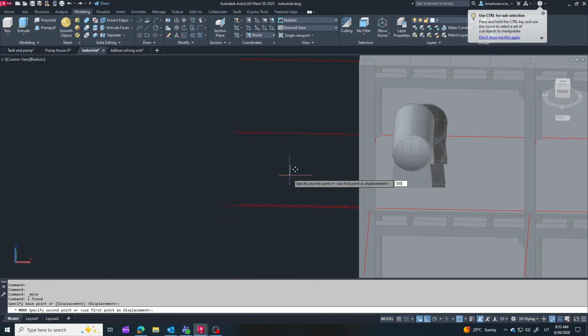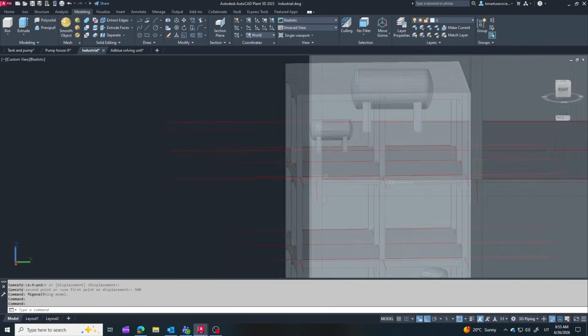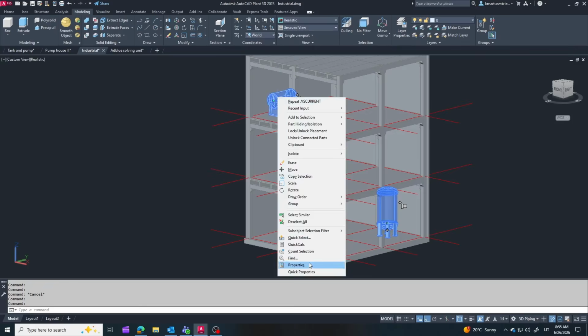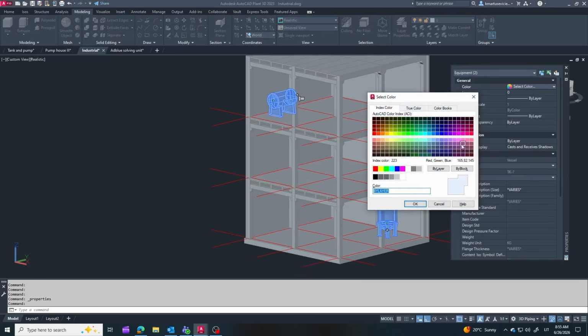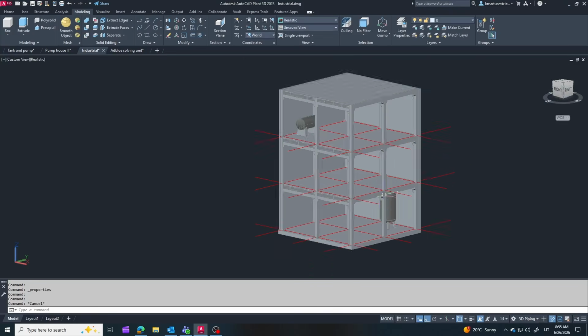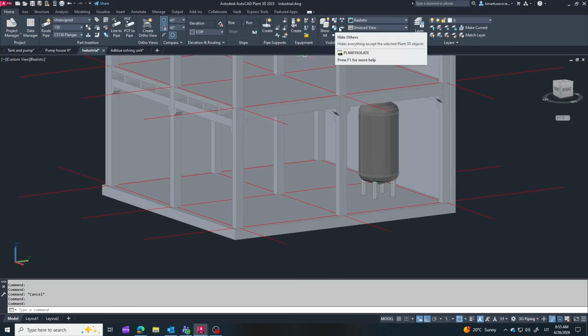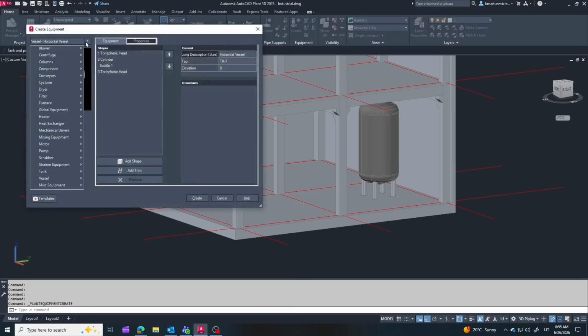Horizontal tanks are a good option when building height is limited. They require more floor space but provide easier access to the top nozzles. Before fixing the final position, always think about piping, maintenance access, and future modifications. A few extra minutes now can save hours later.